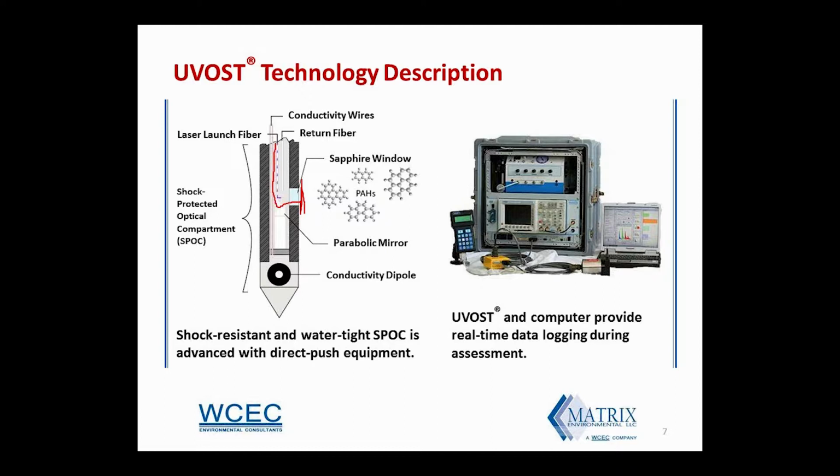Then that fluorescent response from the PAHs is returned to the surface with this return fiber, and then it's processed with the optical screening tool. And you also notice on here we've got a conductivity dipole, so electrical conductivity data are collected simultaneously with the fluorescence data.